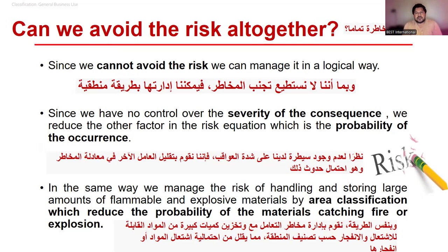We can implement proper safety protocols. We make sure the work permit system is implemented. We make sure the guys are well trained, certified, authorized, and most importantly, they are highly competent individuals and they're the right person for the right job. Same way, we barricade properly. We have toolbox meetings. We have an appropriate set of PPEs, and the PPEs are being used also. We don't work in such areas, especially in confined spaces, without a standby man, without a confined space entry supervisor. We get help through work permit issuers and receivers. It's not like no certified people are there and somehow you are managing.